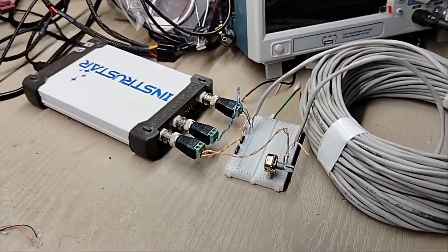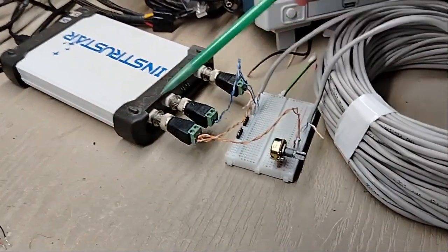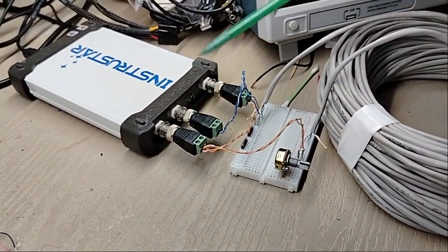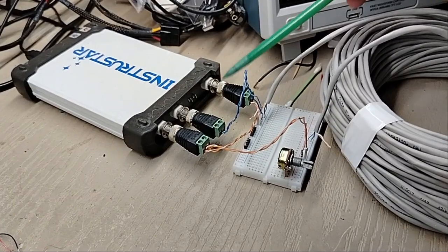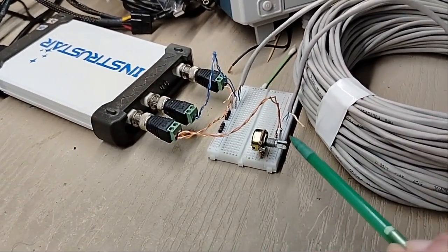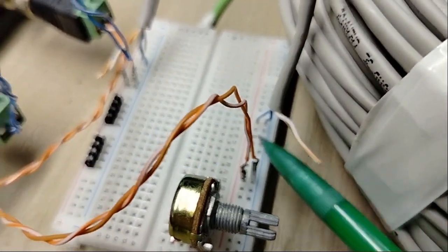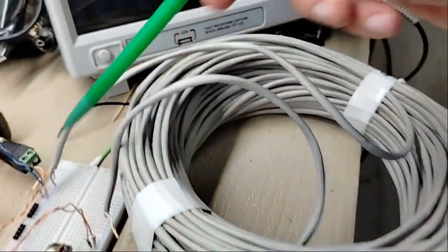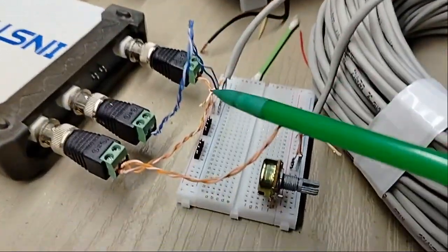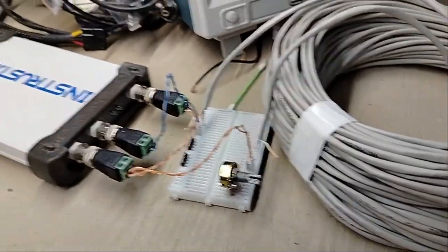So the solution is very simple. In this case, I have this device with the generator, channel number 1 and channel number 2. So we connect it like this. We connect the generator to channel number 1, and then channel number 1 we connect to the cable. So this is channel number 1 connected to the cable and connected to the generator. The second end of this cable goes to channel number 2. So pretty simple. And now let's look at the graph.